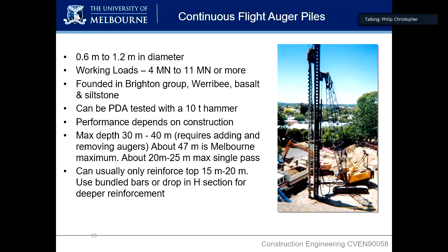Great thing about this one is you won't have to worry about that sand because your pile's never not supported. So it will be cheaper and more economical per pile by far to do a CFA than a bored pile. In all scenarios, generally speaking, but especially scenarios where your material is not self-supporting.